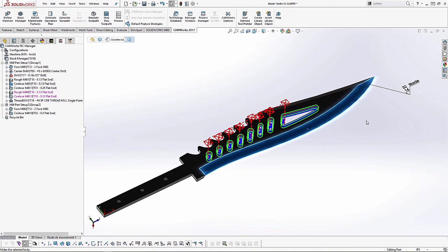For example, if we had a hole with a DIM expert tolerance on it, we can use that tolerance to set the machining strategy. The tightest tolerances we might give to a ream cycle. If we have looser tolerances and we set the threshold, say if the total tolerance is 5 thousandths, then it suddenly becomes a drill cycle. If the total tolerance is 3 thousandths, it becomes a ream cycle. So we can read that data.